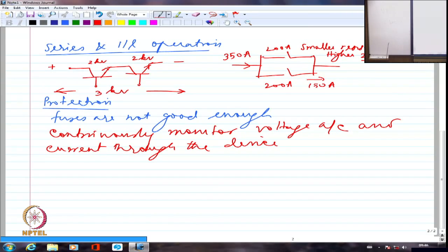In semiconductors, when the heat increases, the temperature increases, and more charge carriers will be released. So the resistance is going to come down further. Unlike metal, where as the temperature increases the resistance is going to increase, semiconductor devices normally have a negative temperature coefficient of resistance.